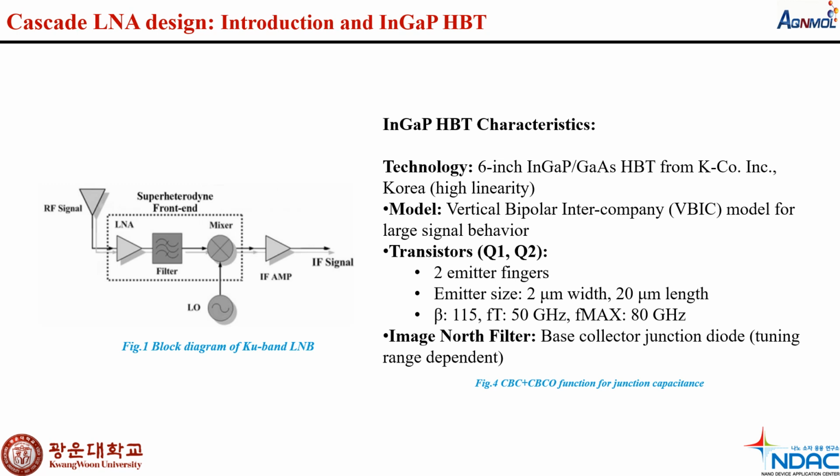It's built using indium gallium phosphide or gallium arsenide HBT technology instead of traditional silicon germanium or CMOS, with on-chip tuning via base collector diodes. This design offers excellent performance and minimizes the noise contribution from the filter.